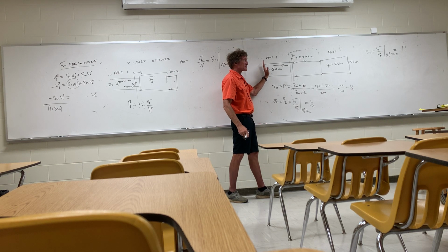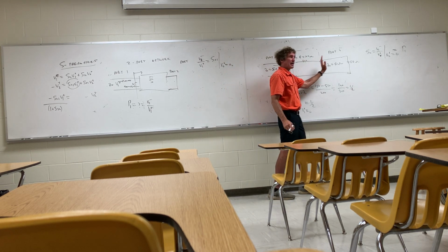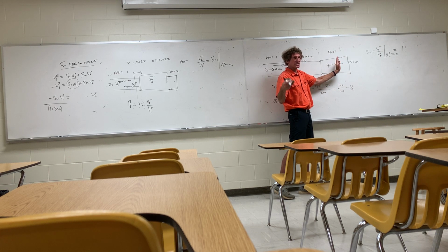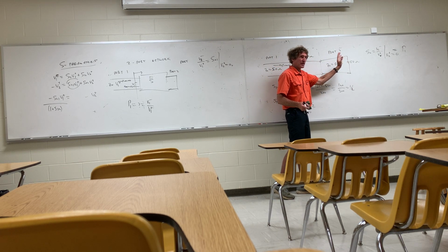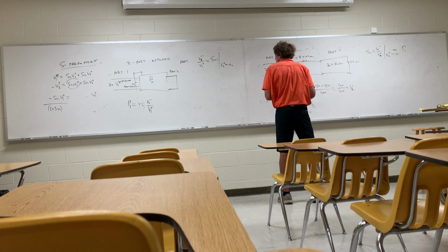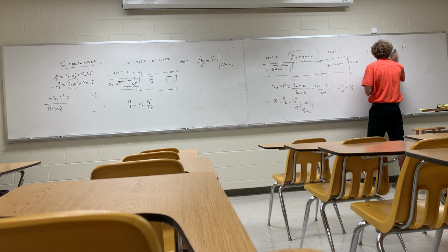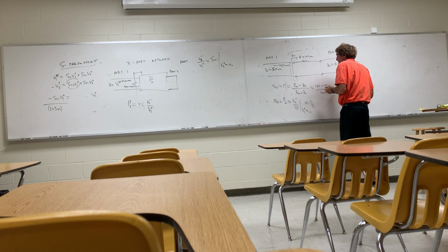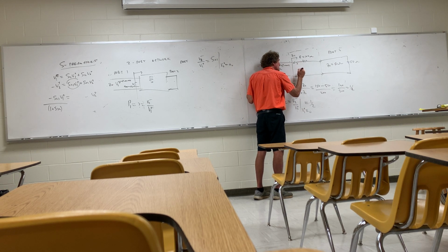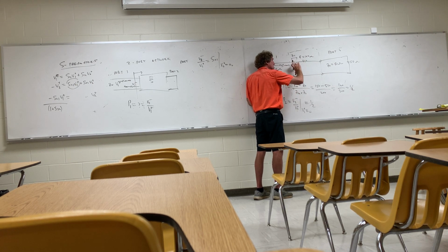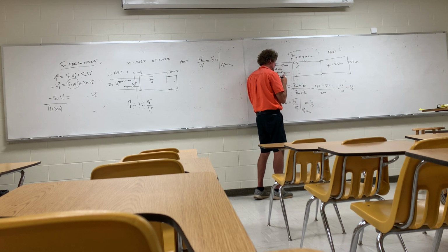I'm saying I've got V1 plus coming in, and I want to see what comes out. That would be a voltage gain. Even if it's actually a reduction, they use the term gain. I want to see what V2 plus is. Do you follow me? Now, here's how you do that. I'll do it right over here. I have a voltage coming in here, V1 plus. There's going to be a certain amount of that voltage, call it V prime, that gets across the boundary. But some of the wave is actually reflected, and I'll get V1 minus. Do you follow me on that?